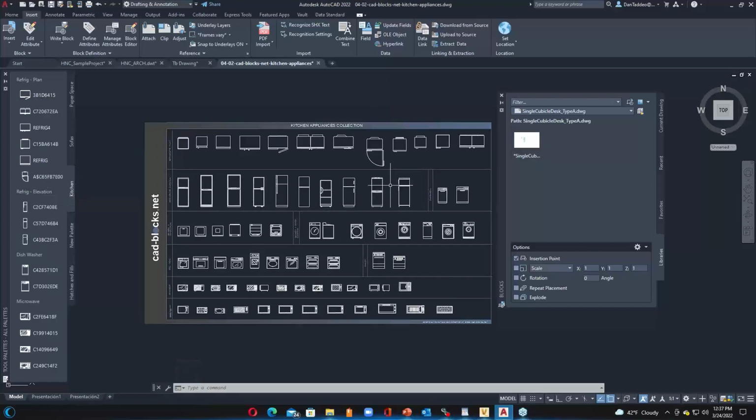So you can have any source of file or any number of files, and it's not restricted to one tab to one file. All right, you can have another file from another directory, as long as it doesn't get overwritten or misplaced. You can drag those blocks directly into your tool palettes.